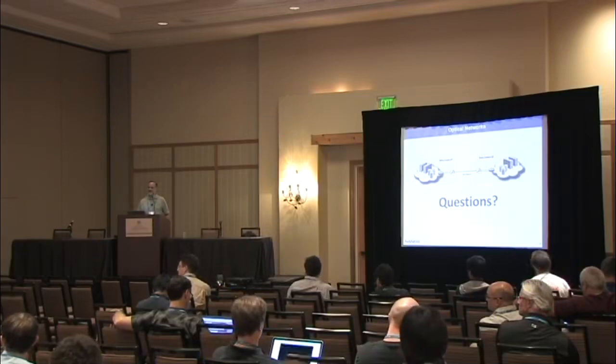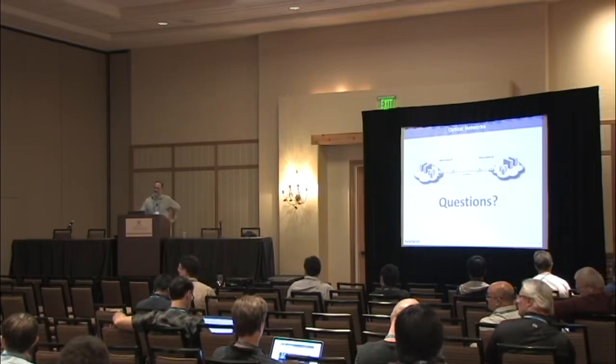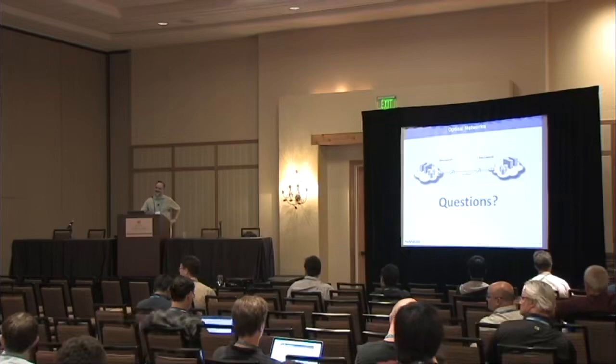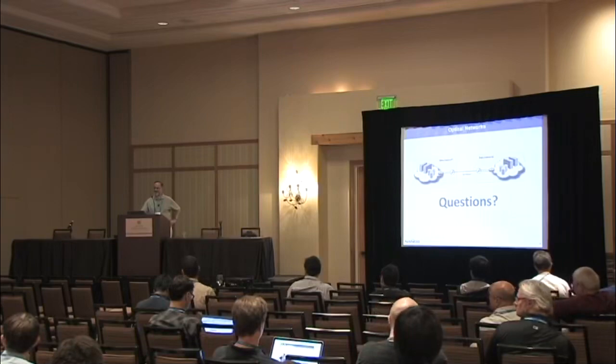I know it's not exactly in your presentation, but I would like to hear something about what yourself and other vendors are doing on the path forward to 400 gig and terabit. And I'd also kind of like to speculate a little bit beyond that. So we're starting to approach some pretty significant practical physical limitations within the fiber. There's only so much bandwidth you can stick on a single mode fiber before the wavelengths get short enough that the single mode starts to behave like multimode. So I'm just kind of curious, what is the far reach of the industry at this point?